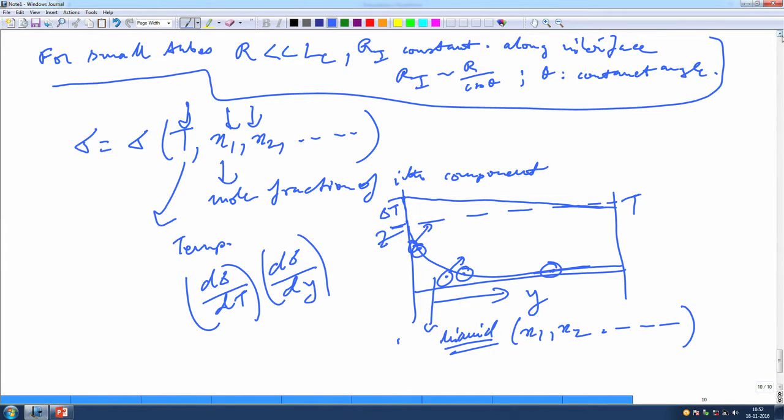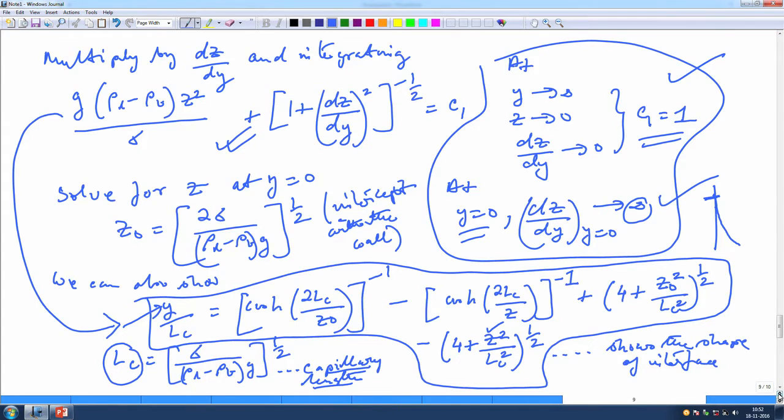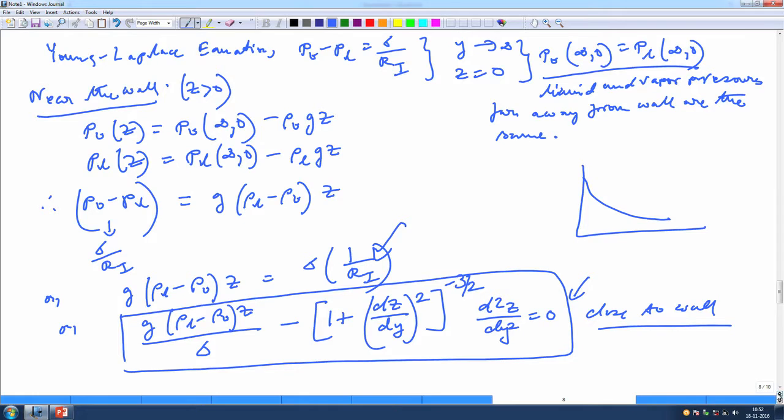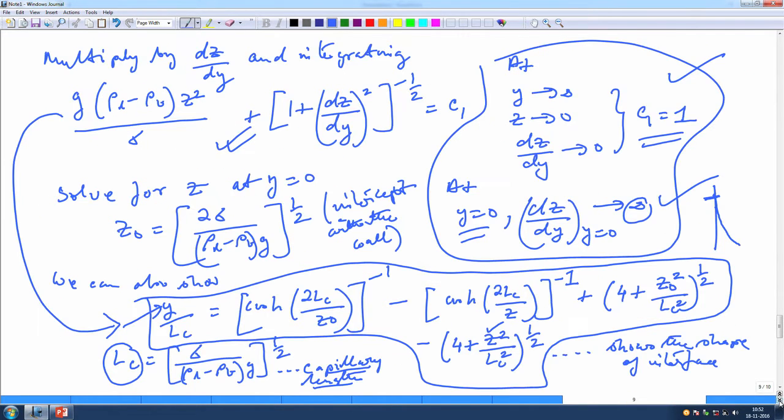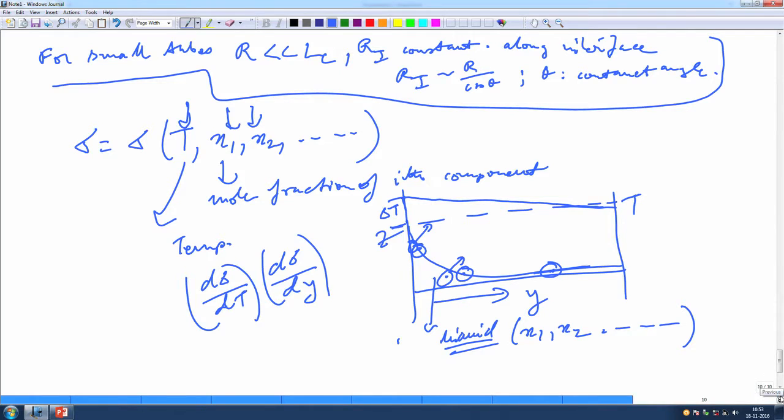Now, in the previous analysis, what did we assume? We assumed that the surface tension was basically constant everywhere, right. When the surface tension is not constant everywhere, like in this particular case that we mentioned, there can actually be flows or velocities introduced within the liquid. From high surface tension to low surface tension, you have a difference in pull, right. So this can actually drive a liquid flow.